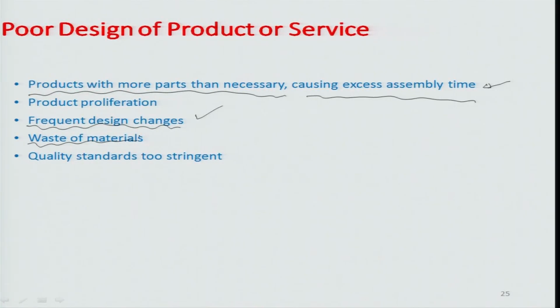of material. For example, let us say there is a need to orient a certain screw into a certain nut, and there are two different modules of the screw, one which has a guide. Let us say there is a conical guided structure on this particular bolt, and the other one is a straight bolt, and this is by design again.